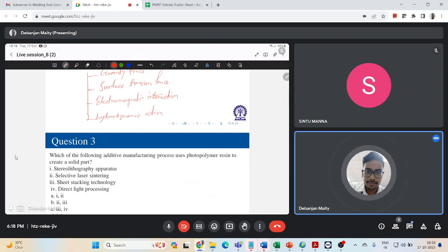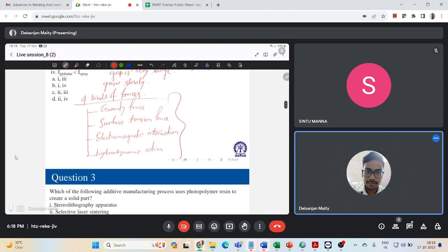So these are some of the different types of forces which are acting in a molten pool. Now, the force of gravity may be a retaining or a detaching force depending on whether the electrode is pointing upward or downward. So this force is acting as a detaching force of that molten pool, right? But surface tension always tends to retain the liquid drop at the tip of the electrode. So these are opposing in nature, right?